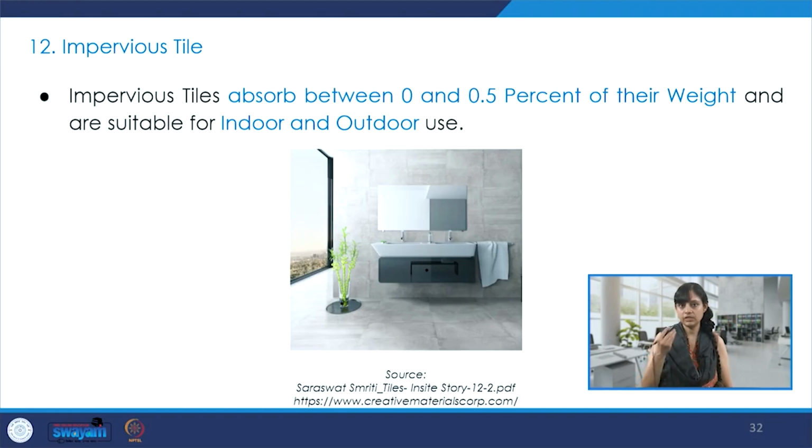There are also impervious tiles. They absorb between 0 and 0.5% of their weight, and they are suitable for both indoor and outdoor use, again depending on where they are getting applied and the percentage of absorption by weight.